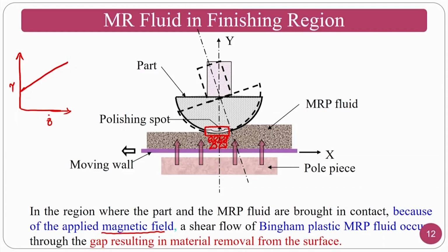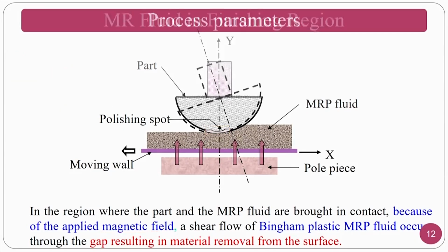You have to apply a certain minimum pressure that is required to push the paste out of the tube. That is the common example. In daily life, you have seen with your toothpaste that only if you apply a certain pressure will the motion of the paste start onto your brush. Similarly here, MR fluid also follows a Bingham plastic fluid.